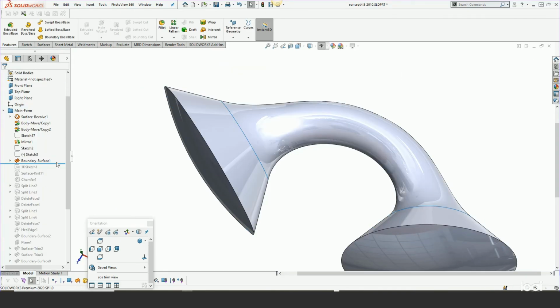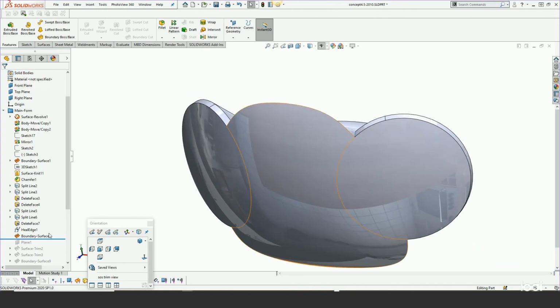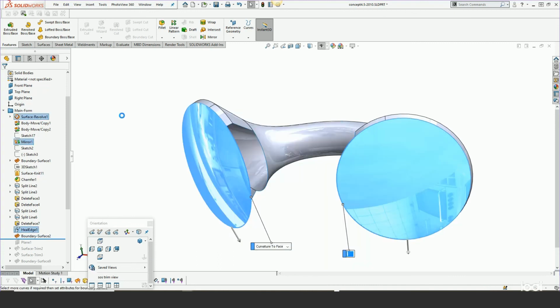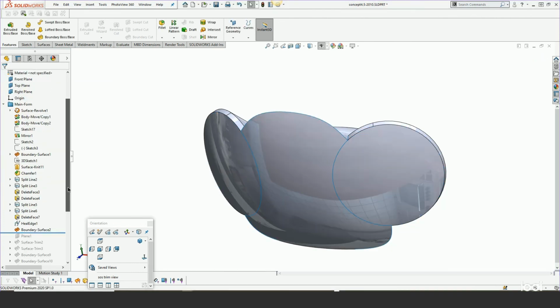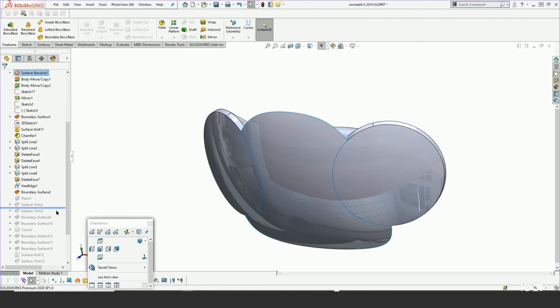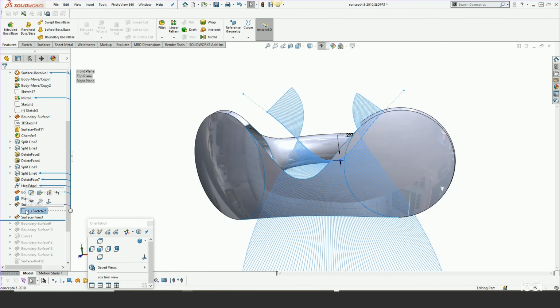So moving forward, we talked about this boundary a little bit also, and my final solution on that was just to do a simple first directional boundary with curve matching on these two revolved faces. And with that, I trimmed both the bottom and the top just using 2D sketch curves in the front plane.